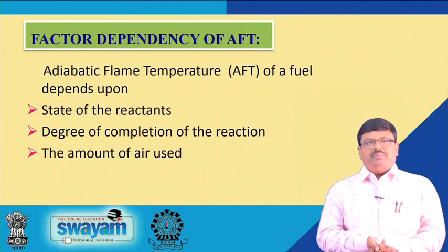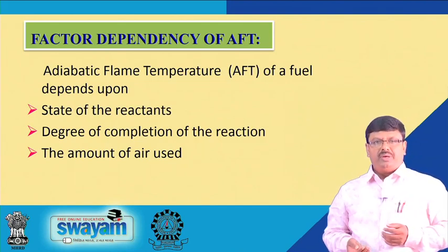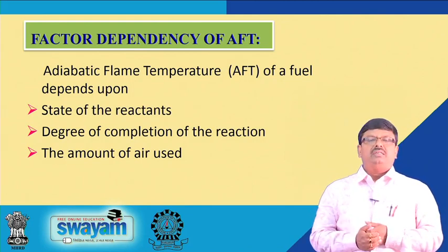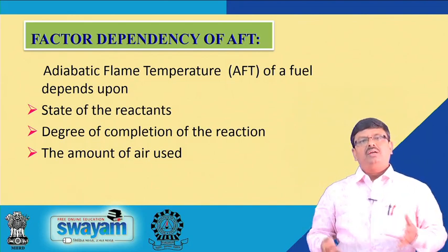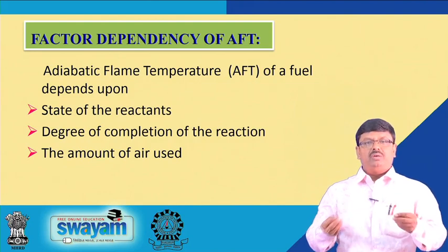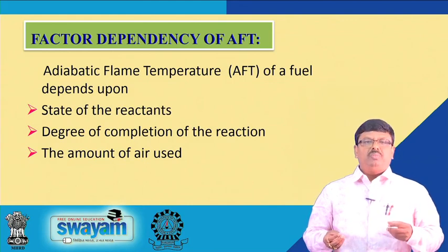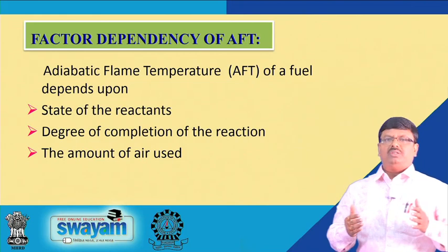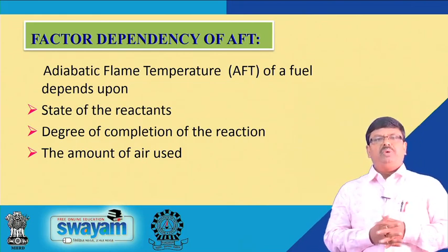Factor dependency of AFT. These are the different factors on which the adiabatic flame temperature of a fuel depends greatly. Adiabatic flame temperature of a fuel depends upon the state of the reactants, that is, the different states of the reacting substances supplied to the combustion chamber, or the combustible gas to be supplied to the combustion chamber for ensuring complete combustion, and the degree of completion of the reaction, that means the extent of reaction, how much of it can take place in a combustion chamber, and lastly, the amount of air used.